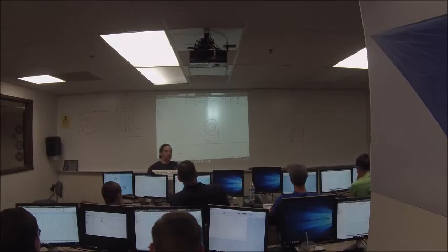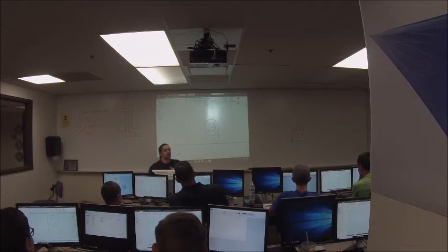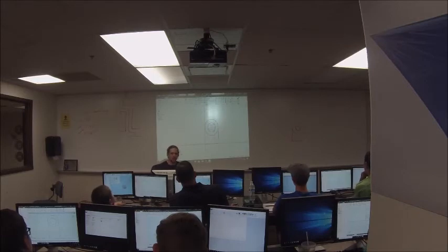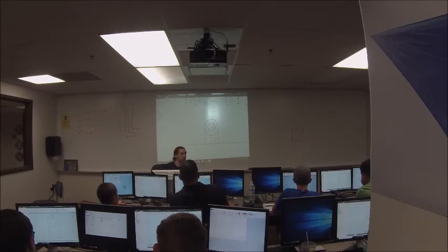So this is something that you'll see. You can do it accidentally pretty easily. Beginners do it a lot. They don't realize necessarily that putting a tangent doesn't actually attach the line to the circle. So in order to do that, you need to place a coincident constraint between the endpoint of that line and the circle. Now, how would I do that? There's a couple different ways I can do it. How could I do that?